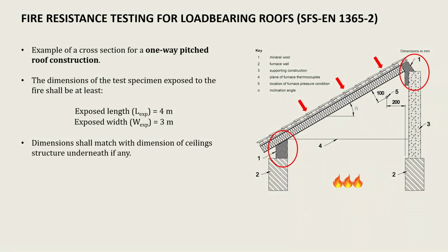The load distribution during testing should replicate or exceed practical shear forces and moments. In addition, the furnace pressure is set 100 mm below the pressure reference line, while the thermocouples are positioned at the lowest side of the specimen's exposed surface.